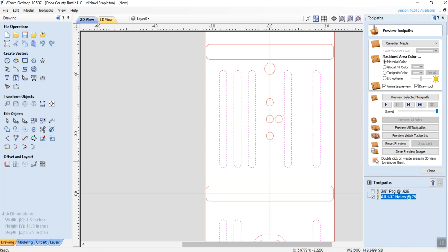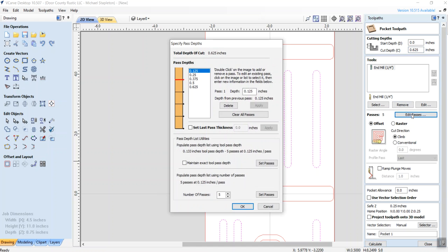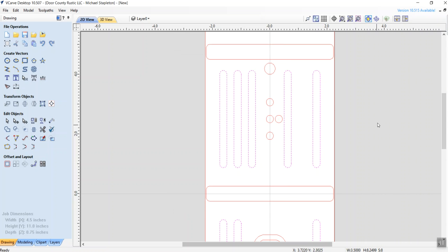So I go up to here again, close, click on the same one here. Those I all want to be 0.625. Any shallower than that, the plywood doesn't stay in the slots very well. Now that one again is PVC, but I did learn that I don't want to go too deep on those because they just leave a lot of dust in the path.